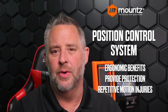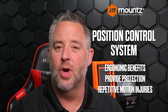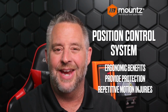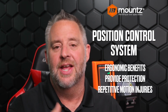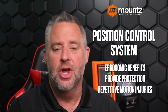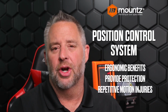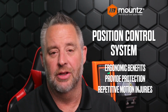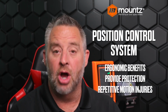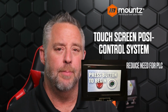So if we're down in the low inch-ounces, a few inch-pounds, it's good to put the tools into a torque arm as well, because now you're getting 100% of transfer of the torque from the tool to the part, and the operator isn't influencing that tightening through any type of side load or leaning onto the tool, where it could introduce some inaccuracies at a very low torque value. So those are some of the benefits that go along with putting the tool into an arm.